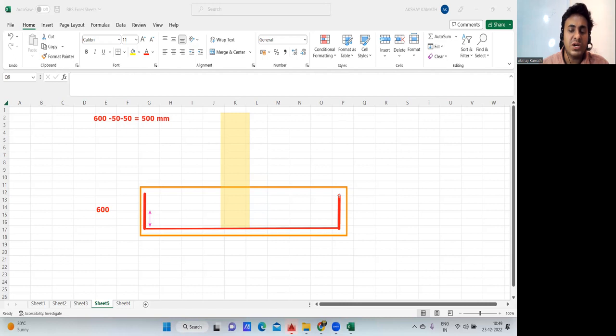That is why some clients say you take two-third of the depth. Whatever answer you are getting here, you take two-third of that. That is why I made you take two-third. That means 500 is correct, and for this we apply two-third. Usually we say two-third is 67%, so 67% only will give the L. So 500 into 0.67, or 500 into 2 divided by 3, will be 333 mm. Practically we try to keep this at 330.